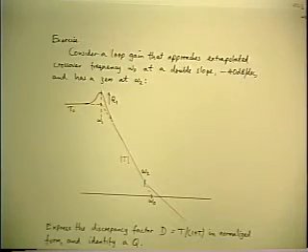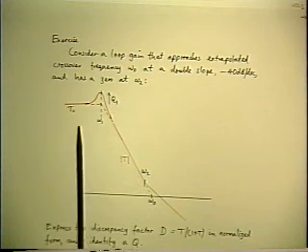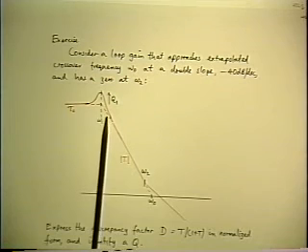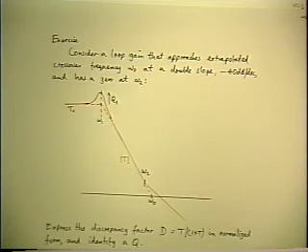Now I want to look at a related problem. This one comes up specifically in the realm of switching power supplies. It's a good exercise anyway at this point. Here's a different shape of loop gain, starting from T0, and it has a second order corner. That is, it has a complex pair of poles, which might arise from a real LC filter, which is part of every switching power supply.